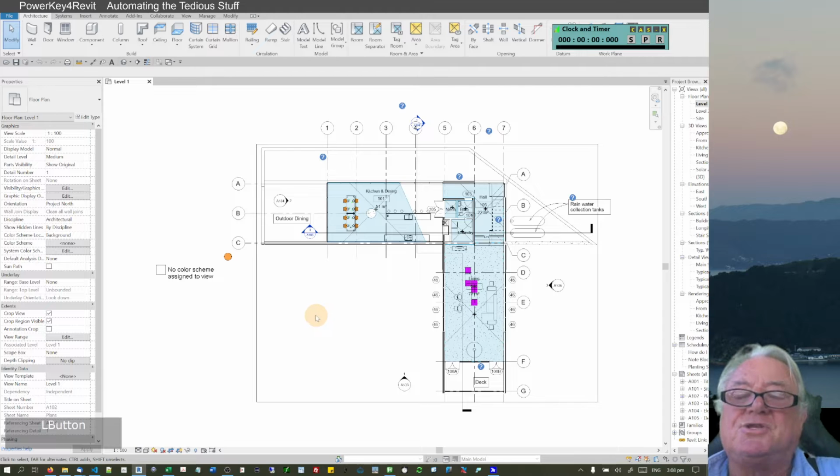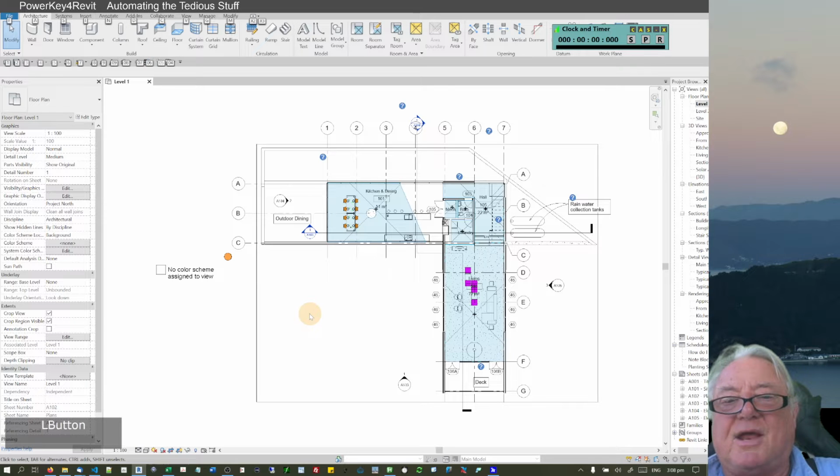As a demonstration, this first one is just to use the region command. We're going to run the region command and see how long it takes us to do. I'm going to type Alt S, and because I'm active over here, I've got to click into the Revit screen so that it's active. Then I can run the keyboard shortcuts. So I'll go Alt F, start the timer, click on that and type R4.